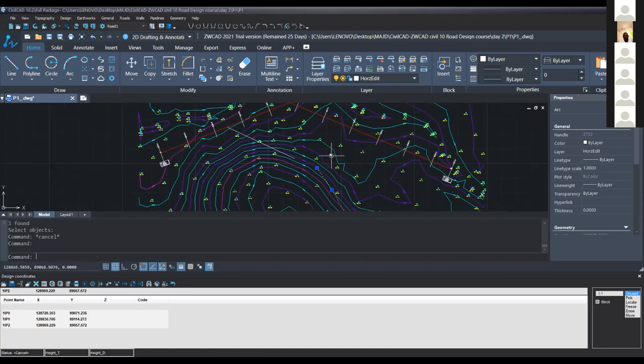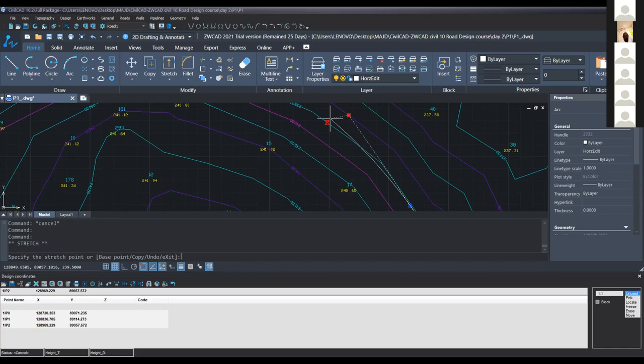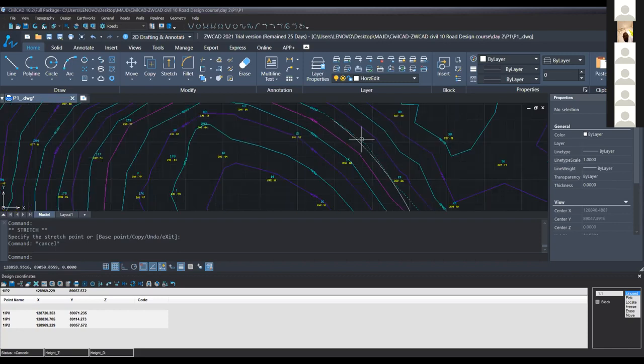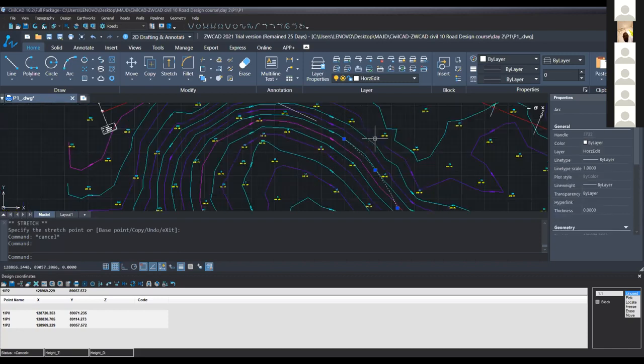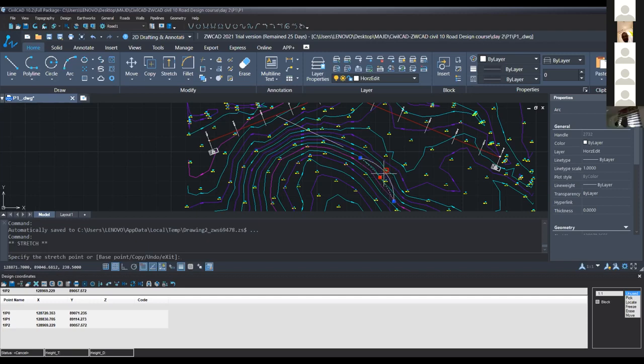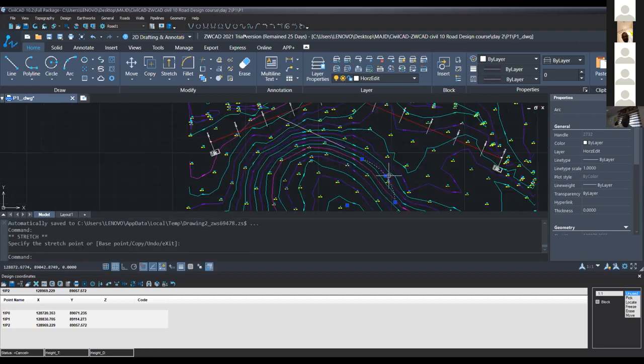So what is the arc? This is the arc. What is highlighted? This is the arc. Yeah, well, see the problem. There's no geometric solution. Can you zoom out? Don't do anything, please. Zoom out a little bit more. Now you have to imagine that it has to have a geometric solution. It means that the tangent and the arc can connect with a tangent point. For example, if you take the middle point of the arc and stretch it a little bit outside, yeah, this one, for this you'll surely have a solution. You have to extract it outside, so it will be a geometric solution.